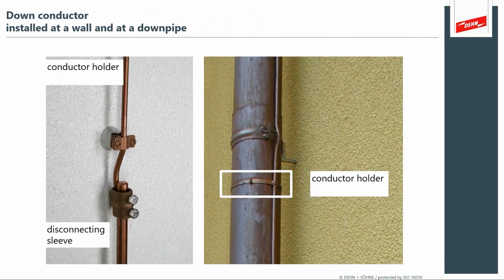So now we'll talk a little bit more about the down conductor systems. The down conductor serves to bring that lightning current to Earth. And that's where a lot of the problems with separation show up: if you're next to this water pipe, you don't just get to run it parallel to it, because it'll flash between that water pipe. In the IEC methods, we also want to talk a lot about how you connect to your earthing system and how you test and inspect.